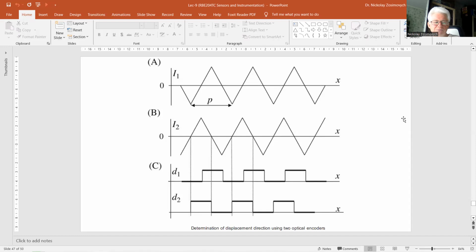The Vernier concept can also be applied in absolute encoders to enhance their intrinsically lower resolution. Details are given for an absolute angular encoder used to control a servo with two disks comprising only 3 binary tracks each. A resolution of 1.6 degrees can be achieved instead of 45 degrees with a conventional 3-bit code disk.